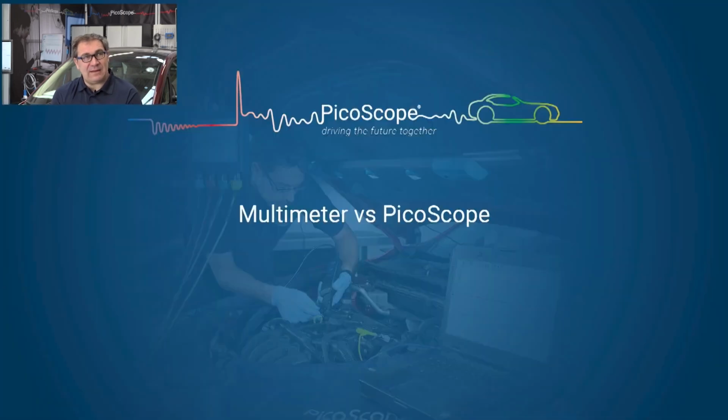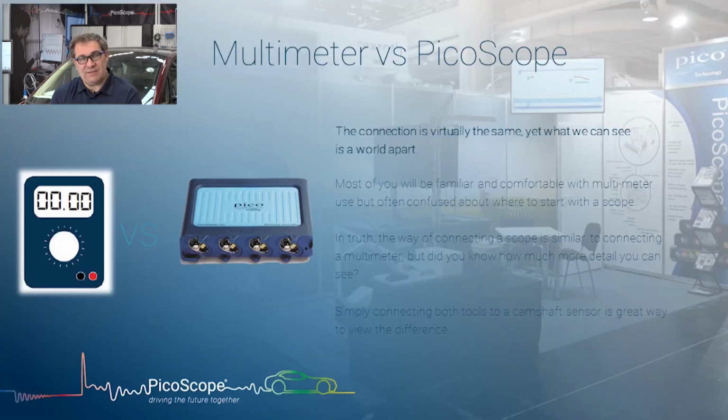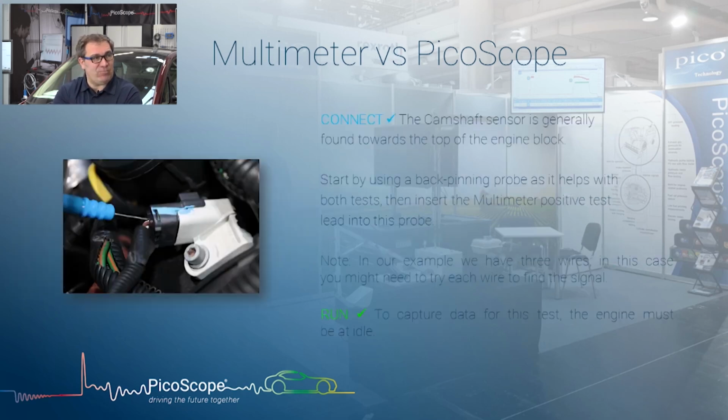So we're going to have a look at multimeter versus PicoScope now. And I'll just take you very quickly through the process, and then Phil's going to work live on vehicle. So effectively, as I just said, this is exactly the same as using a multimeter connect to a component, but what we're going to see in the waveform is so much more valuable. Phil's going to show us a camshaft sensor. So let's just have a quick look how we're going to connect into it.